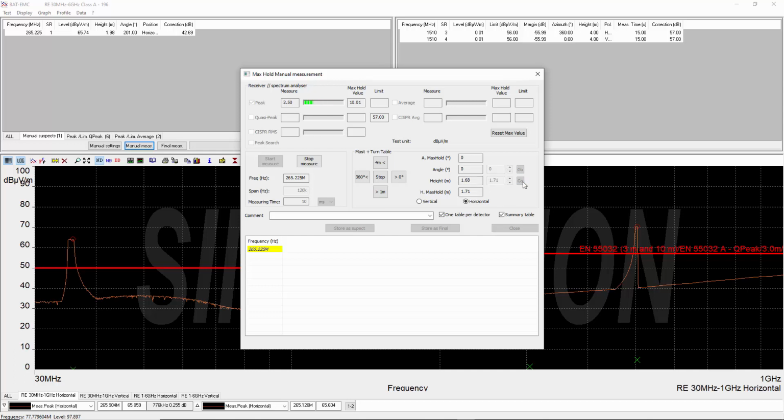We've asked some customers as far as what algorithm they're using and the maximization effort, and this corresponds well. However, we have had some customers who say they would like to use the quasi-peak detector, and I had to remind them that the quasi-peak detector is extremely slow. The minimum charge time is about 1 second, and therefore we only use the quasi-peak detector for final measurements once the positioning systems have stabilized. If you were to rotate or change an antenna mast in 1 second, you could travel very far.